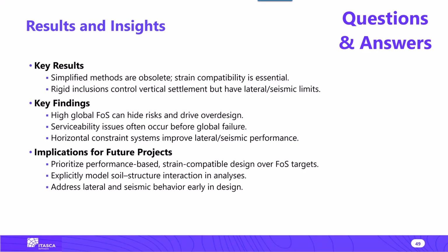Yeah. So, as usual, it's a combination of science, art, and let's face it, gut feeling as well. So there isn't a comprehensive answer that is valid for every situation. But in general, the procedure that I tend to follow is the following. You have a CPT profile, better if you have a seismic cone for which you have the direct measurement of the shear wave velocity. If you don't, you can use several correlations, Robertson, for example, or Mayne, or others that give you an idea about the shear wave velocity profile.